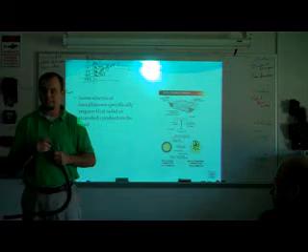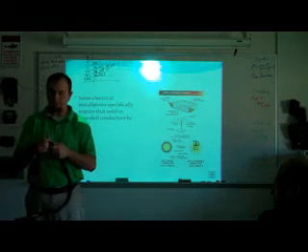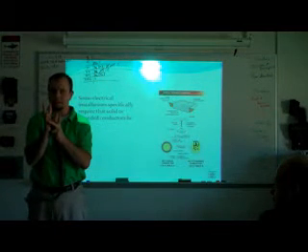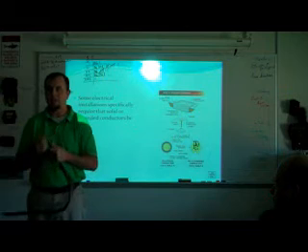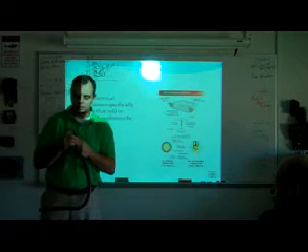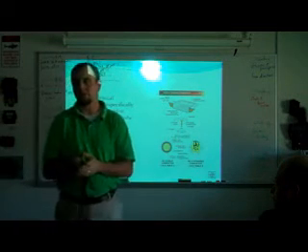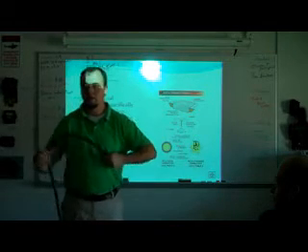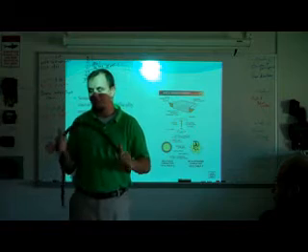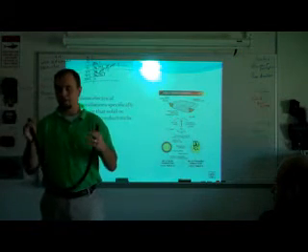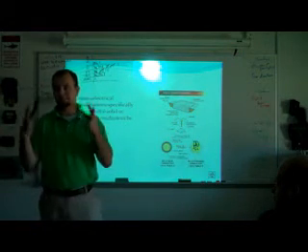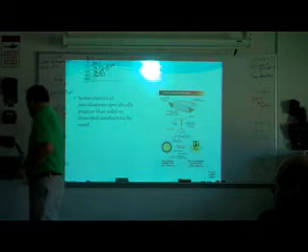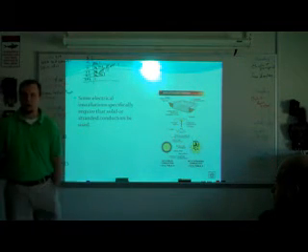The only bad thing is when you go to strip it back and you've got a bunch of hairs sticking out. That makes it kind of a pain in the rear. This one's about 14, but you can get them in smaller. Now, will it say what size the stranding is on the sheathing? It won't. It just tells you how big the overall size is. That would be something you'd have to work out with your supplier, I guess.